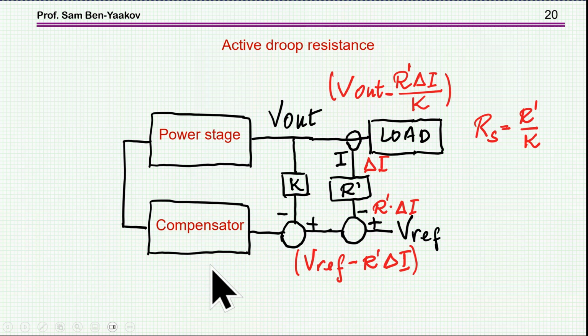Now the idea is the following. We are measuring the output current, and as a function of this output current, reducing the voltage by feedback. What I'm showing here is the original power supply control. This is the power supply, the reference, the summing point, compensator, modulator, and power stage, and that's the output voltage. K is the voltage divider between the output and the reference.